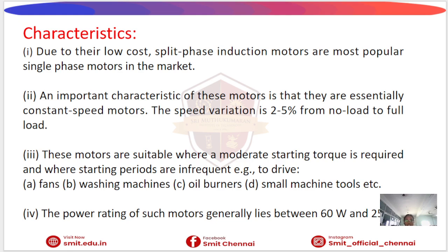Characteristics of split-phase induction motors include low cost and wide use, and an almost constant speed. Speed variation is only 2 to 5%. They have moderate starting torque only. Power rating is usually 60 watts to 250 watts.